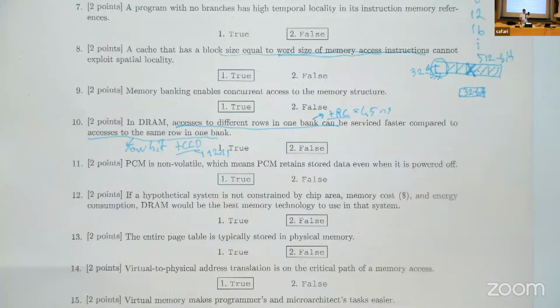Not exactly like that. It's just that when you have a row already enabled and you want to access another row, you have to first precharge the bank, like close the open row, and then activate the actual row you want to access. And you have to wait a very long time to do those operations. But if you're accessing a row that you have enabled, that means you're servicing that access from the row buffer. So it's already enabled. You have the data ready to be pushed through the I/O, essentially, out of DRAM. That's why it's much faster.